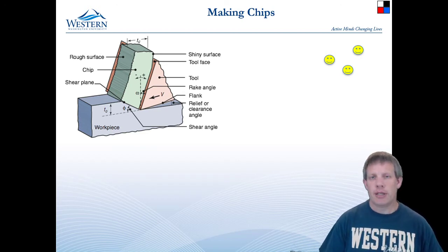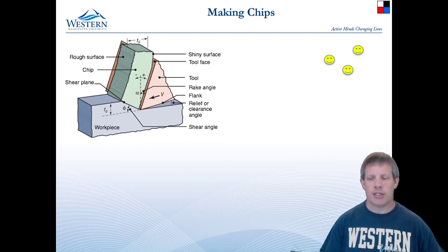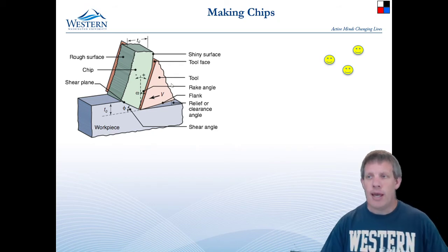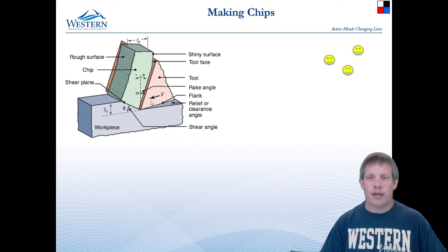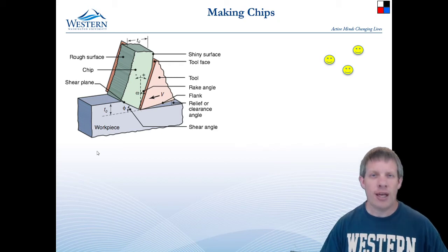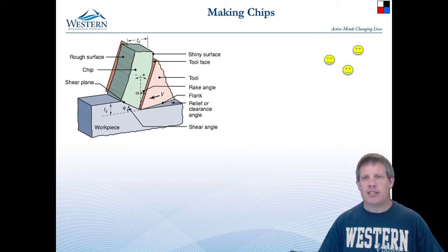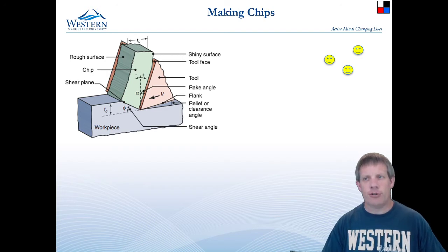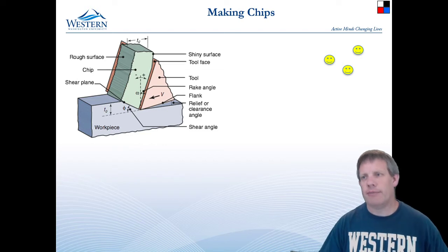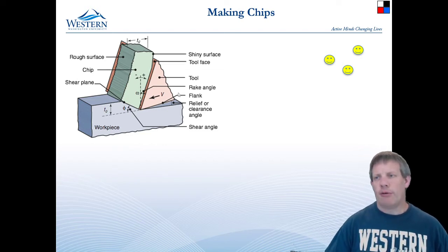And so we're going to spend a little bit of time on machining processes just because they are very common and also some of what we get. Now remember, as the tool cutting edge moves through the material, it moves through with what we call the cutting speed. That's how fast the cutting edge is moving through. If you remember way back to 231 and maybe 332, the cutting speed has really funny units in the imperial system. It's surface feet per minute. And so feet per minute is what we're working with there.